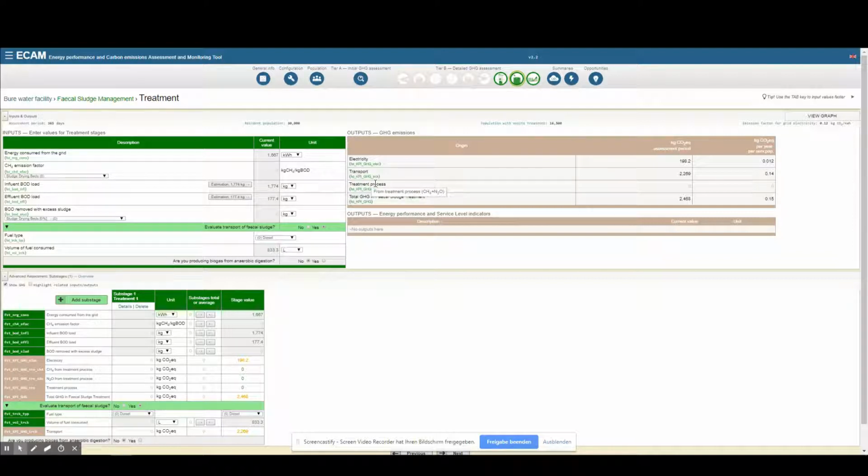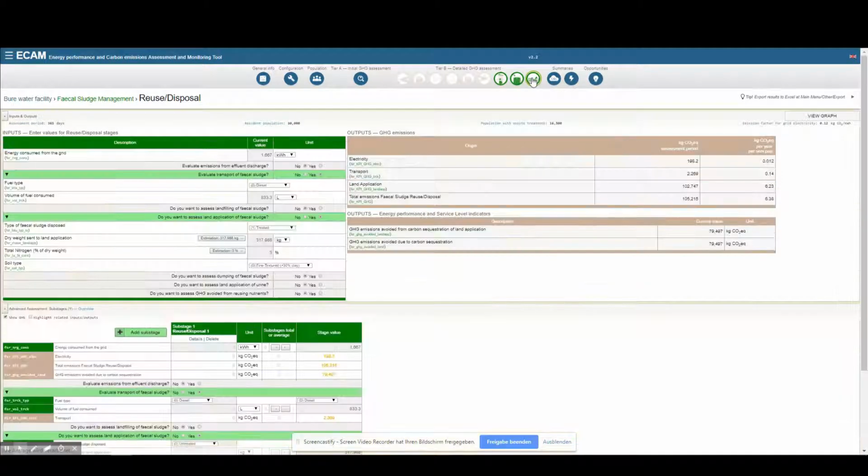Here actually it is striking that no greenhouse gas emissions arise from the treatment process. This refers to the methane emission factor, which equals 0, since the sludge drying beds have no emission factor. It is just 0. So this method doesn't require electrical energy, but its disadvantage may be that it is only applicable during dry seasons. Anyway, the treated sludge is disposed in the last step.